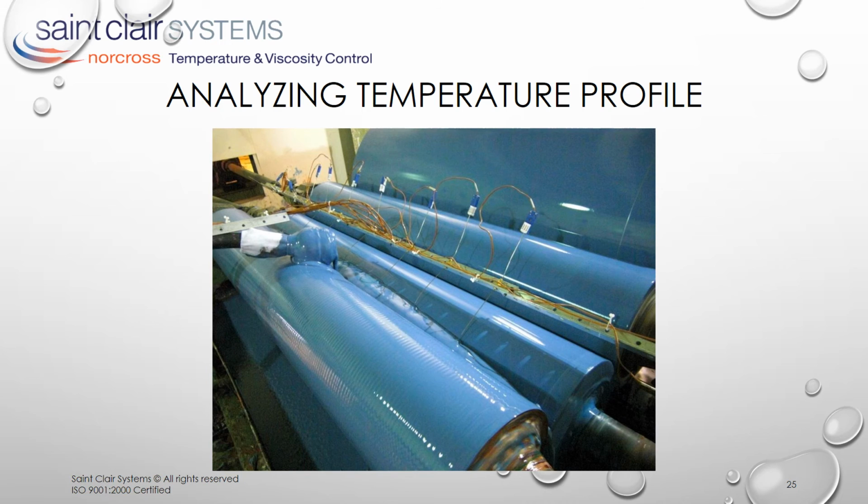Analysis of such a system requires a different approach to measurement, as shown here, where we can see the probes of the data collection system in place across the nip. This is the last opportunity to measure coating temperature prior to application and allows us to identify temperature variations from edge to edge and over time, or head to tail on the coil, which results in variation in DFT. We refer to this as the thermal profile of the nip.